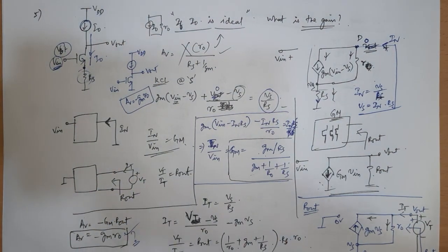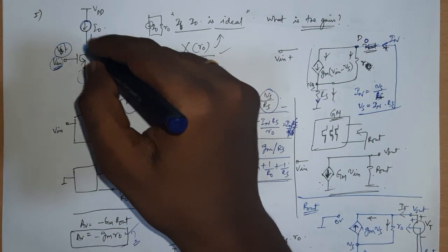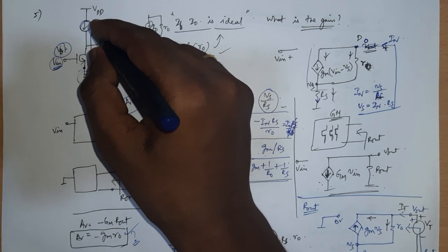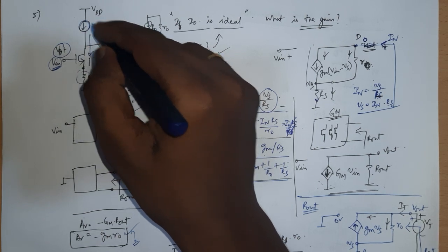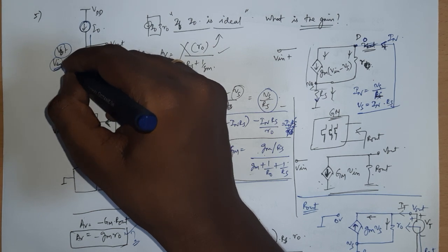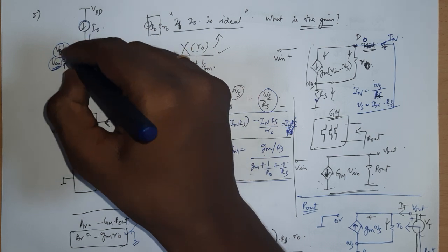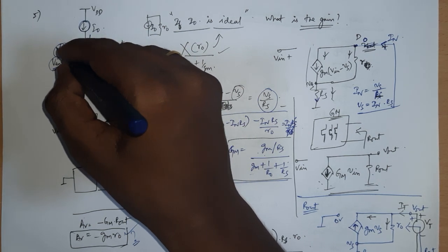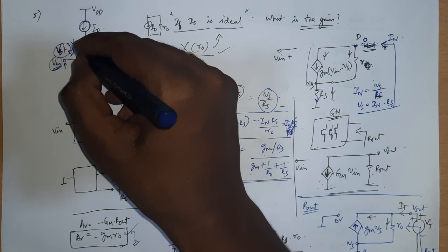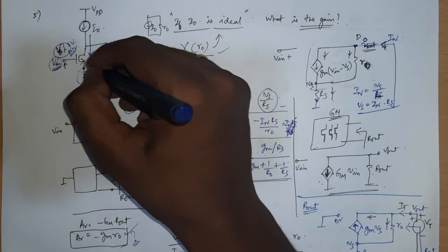Whatever signal you apply to the transistor, as long as you have this DC current flow, say you think of incrementing this node by 0.1 volt, the current is still going to be I0. Say I have a bias voltage of 2 volt here, and now I give 2.1 volt, incrementing slowly by 0.1 volt, then also the current through the resistor is I0.